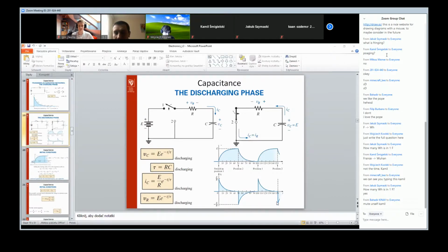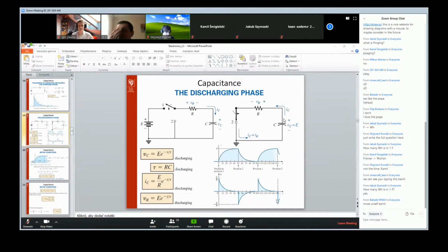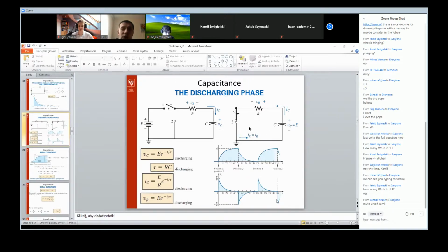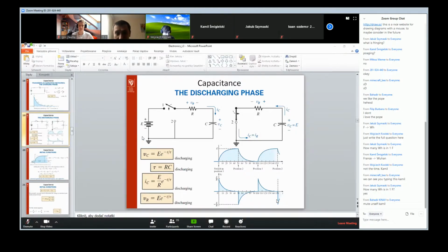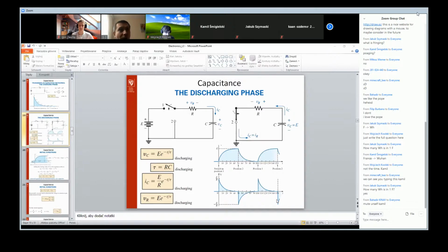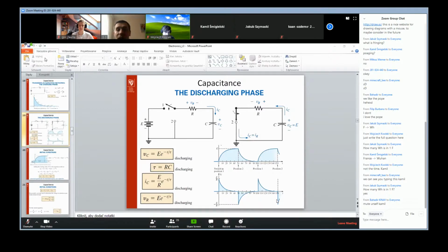It is very, very dangerous according to the noise, in fact, for noise in electronic circuits. You have to remember, anytime you have electronic circuits which consist of capacitors, we can expect peaks, in fact, of the currents, especially if we have some switching elements, for example DC-DC converters.